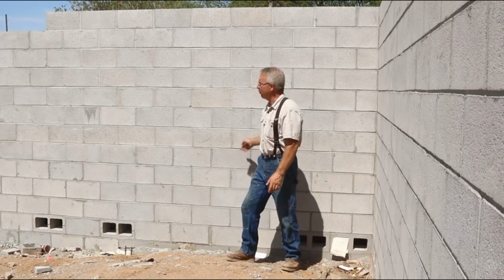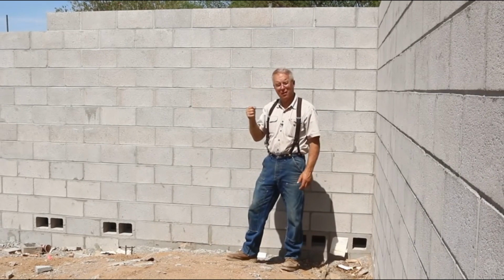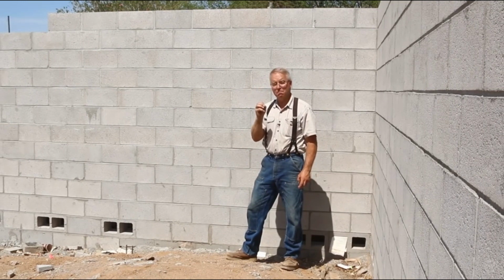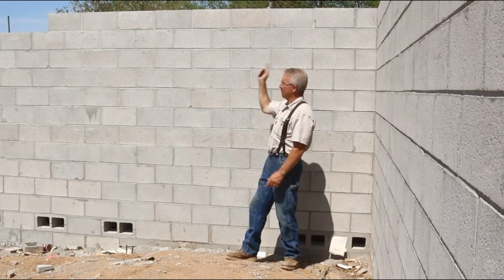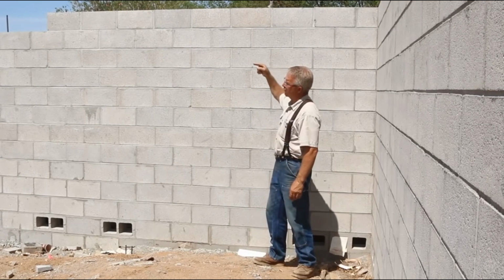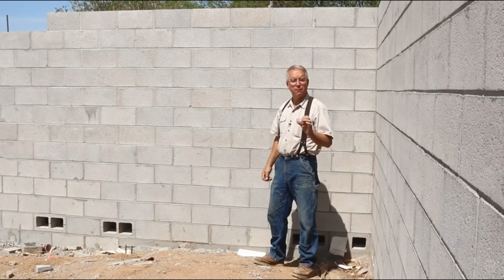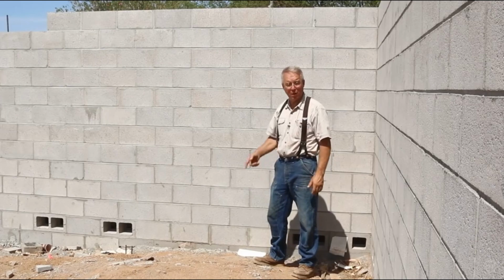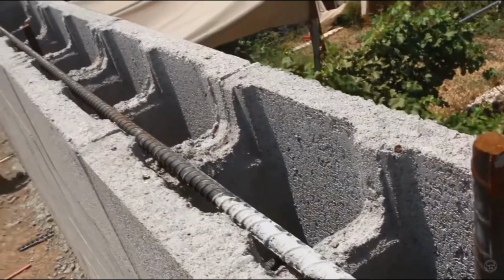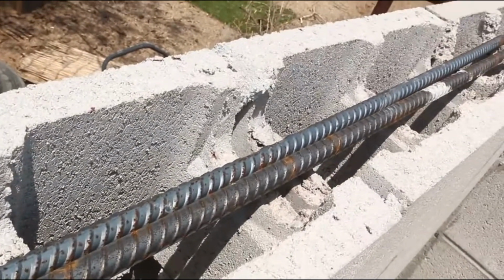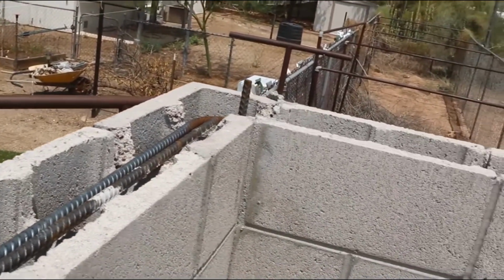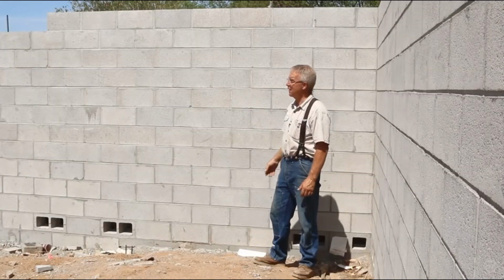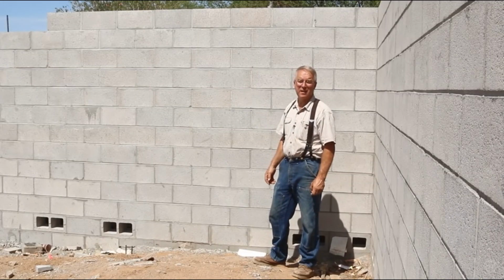And when you put one every 40 inches down 500 feet, you've got a lot of beams standing there, don't you? Now, the third component to the strength of this wall is the bond beam, which occurs in the top course. The top course of this wall is composed of bond beam blocks, where the webs are knocked out so that rebar can be run continuously down the top of this wall and then grouted into place, creating a concrete beam at the top, tied to the concrete beams every 40 inches, which makes a very, very strong 8-inch CMU wall.